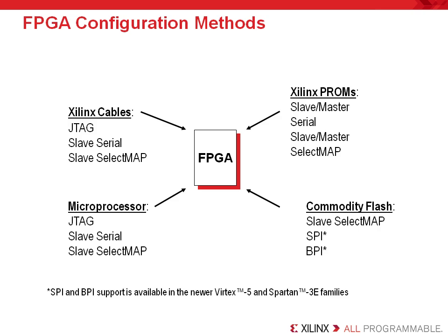There are lots of configuration modes you can choose from. They are all equally valuable and allow our customers to choose a configuration scheme that is right for their application. First, users should always consider configuring their device via a Xilinx download cable. These cables allow the user to reconfigure their FPGA with only a download cable on their computer. The configuration modes that use these cables are used primarily for prototyping and debugging. These cables are low cost and are typically used to configure the FPGA in a JTAG configuration mode.